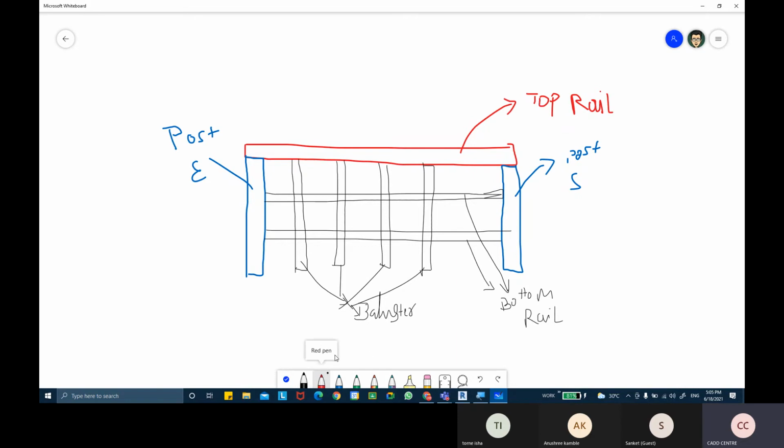So there is more editing of railings. We can edit the posts of the railing, the bottom rails, the balusters, and the top rail. All these parameters you can edit and create your own railing styles. What I want you to do is try these parameters first and understand them, it's really important. Then in the next class, on Monday, we're going to do the bottom rails and creating our own baluster styles,